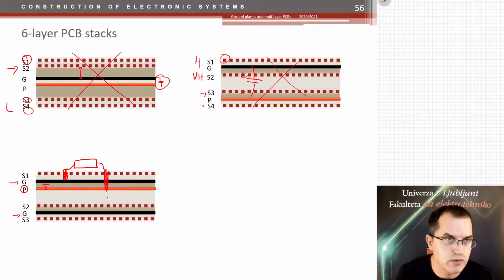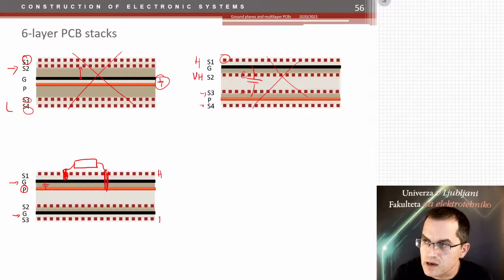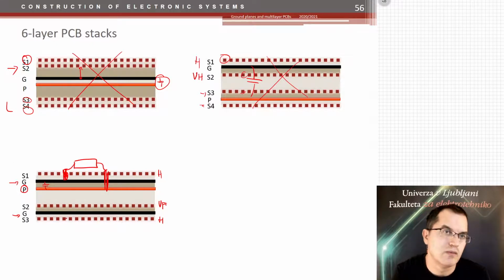The power would be very good at high frequencies with low impedance. All the tracks on top can now be used for high frequency signals. Even very high frequency here, because that one is contained within the sandwich, and here you can route the most high frequency signals.